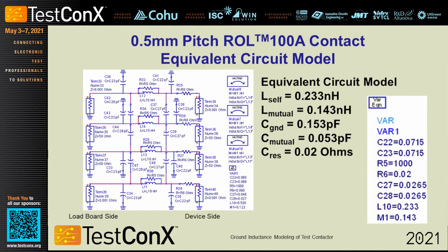Typically, the contact resistance is more important at the device side because you're dealing with, in some cases, matte tin, and the contact resistance between a gold surface and matte tin is a lot higher than maybe the load board side where you've got a gold-plated pin or some other material with a gold-plated trace, and so the contact resistance there is minimal compared to the device contact resistance. So we've added that to generate more of a FET model for FET devices, because in that application, the RF signal out is also the same path as the DC voltage in or current in.